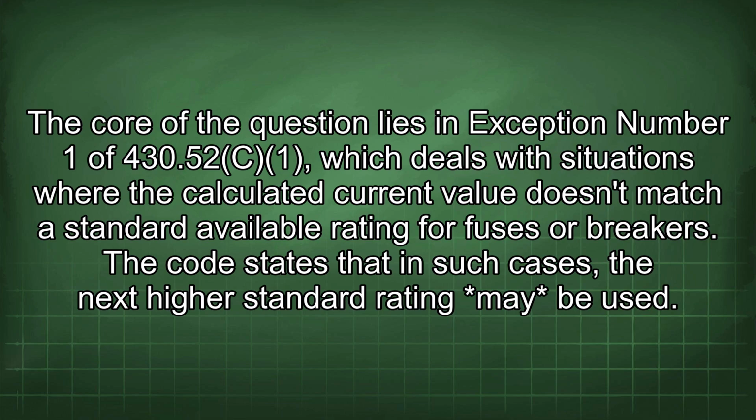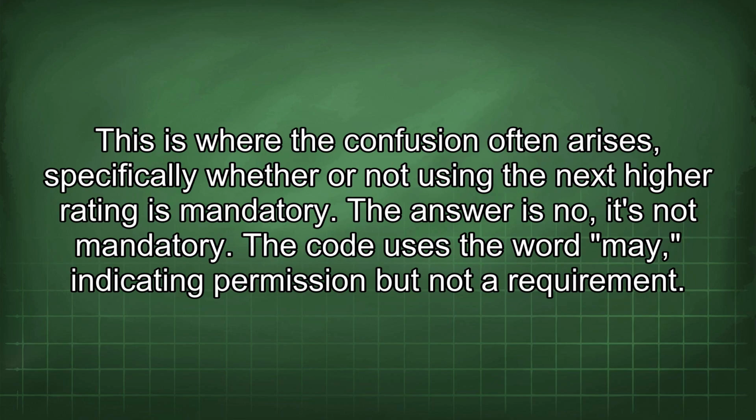The code states that in such cases, the next higher standard rating may be used. This is where the confusion often arises, specifically whether or not using the next higher rating is mandatory. The answer is no, it's not mandatory. The code uses the word "may," indicating permission but not a requirement.